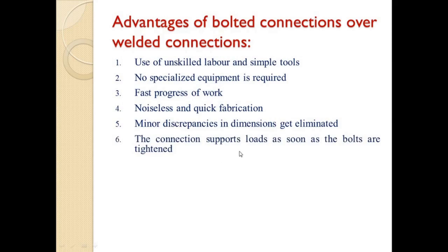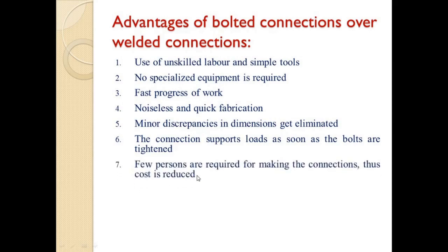Next, the connection supports loads as soon as the bolts are tightened. For welding, we have to wait for some time for cooling of the weld. So it is not the case in bolted connection. Next, few persons are required for making the connection, thus cost is reduced. We can use unskilled labor, so the requirement of persons is less, and therefore it reduces the overall cost of the project.